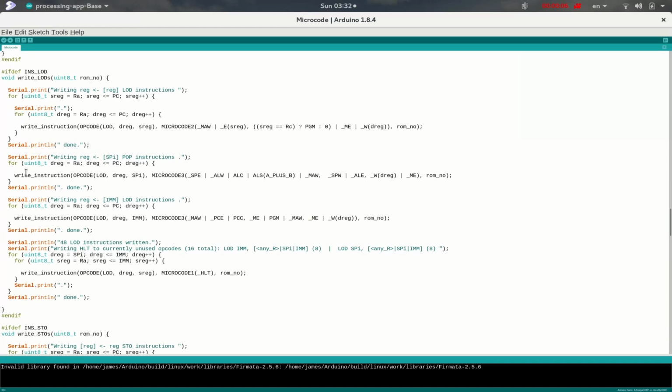And so assuming that we also handle these pop instructions, which we'll get to in a moment, that basically is the entire list of load class instructions that our CPU will support. And so any other combination of bits in an opcode, where the most significant bits correspond to the load class, i.e. 0, 1, we consider those to be illegal instructions. And in fact, those are any instructions where we are loading into the immediate operand or loading into this stack pointer with auto increment operand.